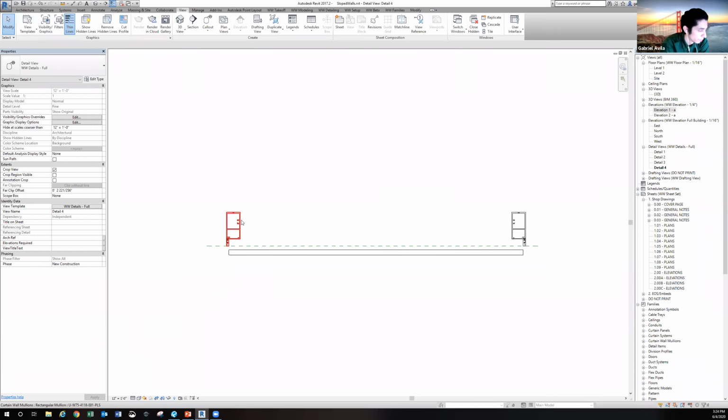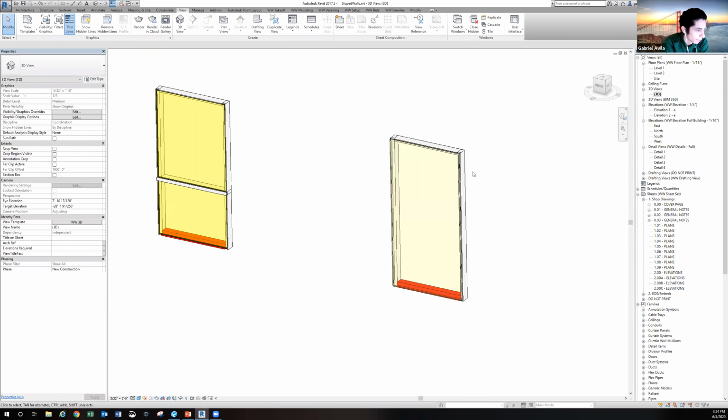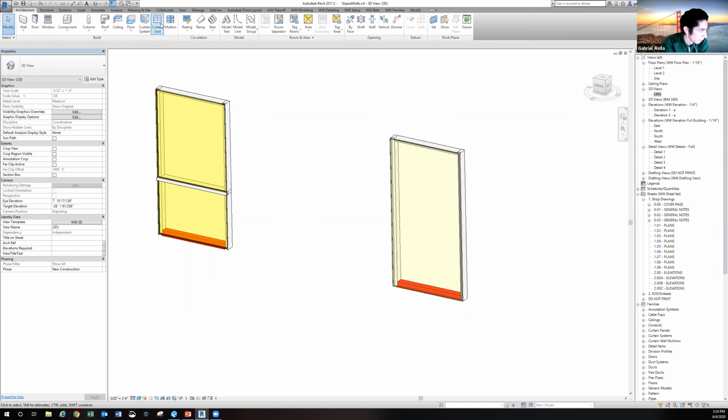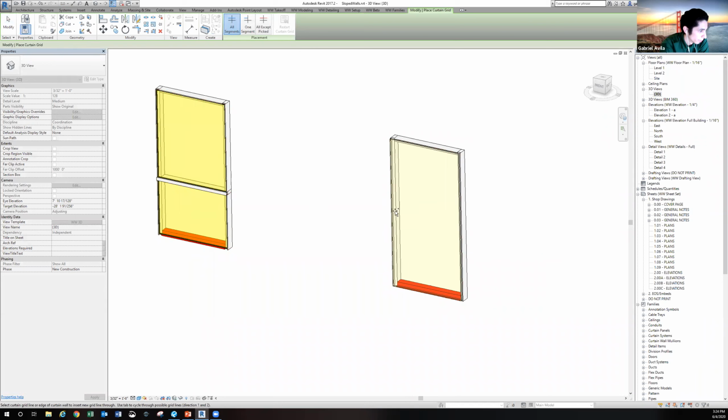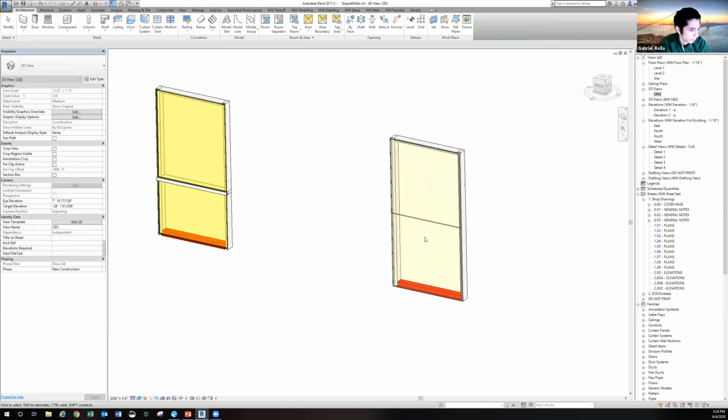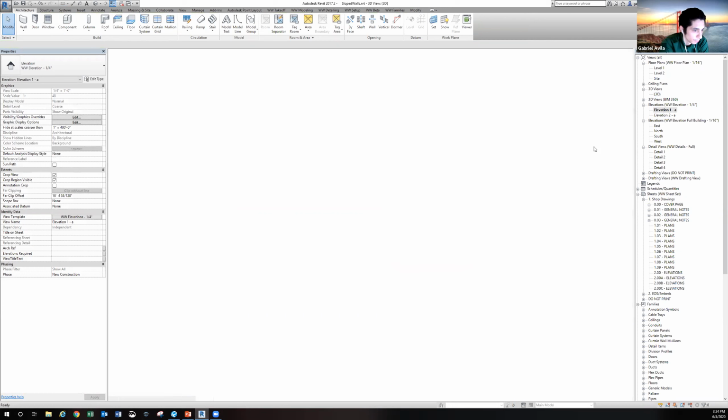So those are your mullions for your jambs. They're verticals. You would switch those to verticals again. And then say you wanted a horizontal like this one. What you would do is go to Architecture, Curtain Grid, then put a curtain grid in there. I just placed one arbitrarily, but to get it to exactly where you need to, again, the section